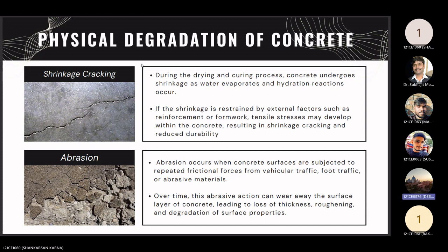Next one is shrinkage cracking. While curing and drying of the concrete, shrinkage occurs due to evaporation of water and many other hydration reactions. If restraints are imposed by reinforcement or other external factors, then tension develops and cracking occurs, reducing the durability.